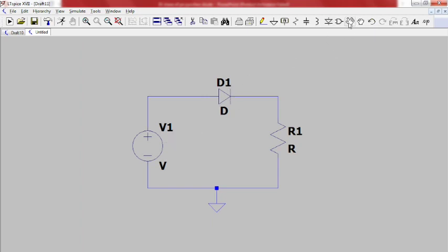By using the hand symbol, move and drag, by clicking the move symbol, we can, suppose we want to take out this diode, just click on the diode and we can take it out from the circuit. If we want to rotate and place it in the correct position, just press Ctrl R and keep it in the right position. Similarly, we can take out the component.